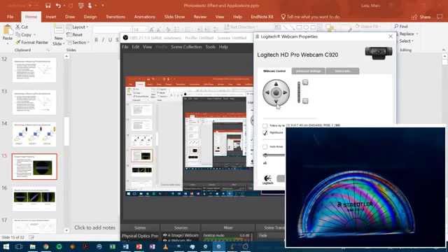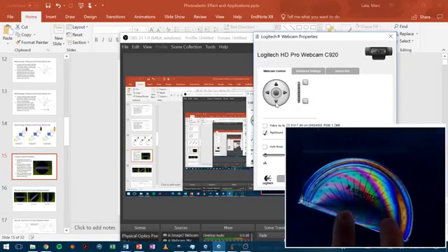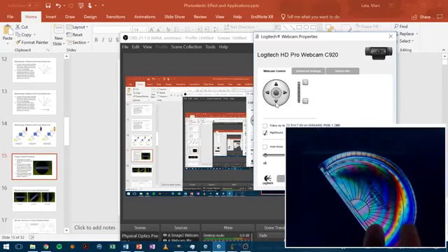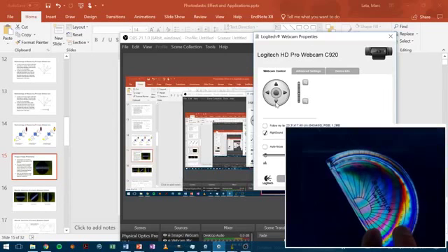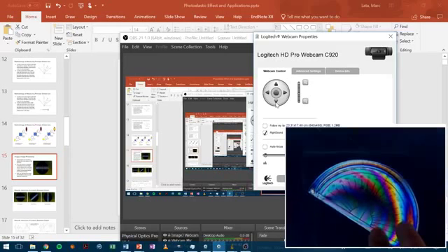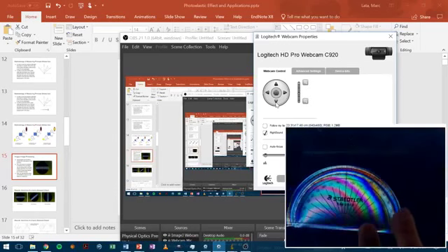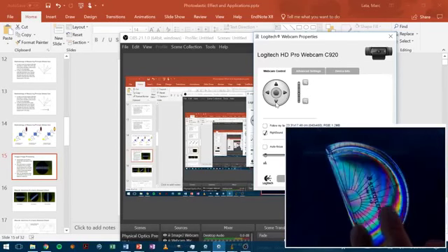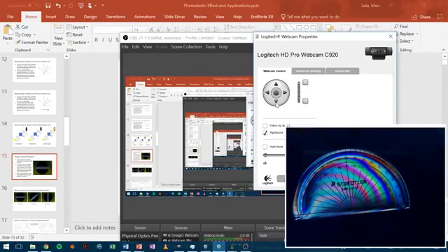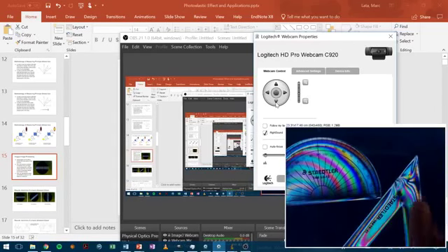Okay, so here's our protractor that you saw in the presentation. And what you'll see as I rotate it, these isoclinics, that dark spot, will move as the predominant direction of stress becomes aligned with the polarizers. As we rotate, the direction of stress will rotate with the object and become aligned with the polarizer. This is because, as mentioned earlier, these have to be considered as a collection of crystals themselves. So the predominant stress direction actually changes as a function of the angle.